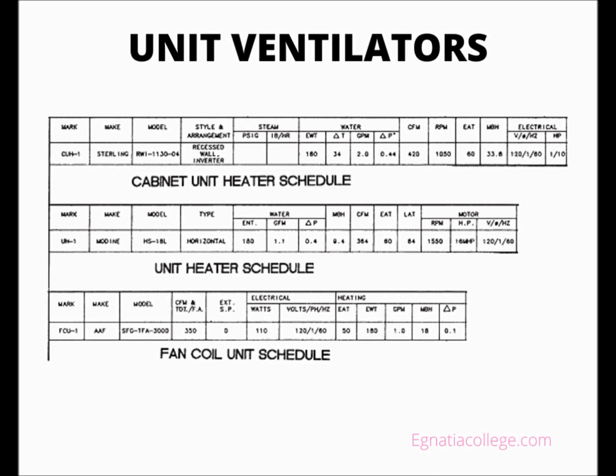The unit ventilators are only a few feet long. Yet the plans show a continuous string of equipment of some sort along the exterior walls of the classrooms. Although not labeled anywhere on the plans, the equipment is bookcases. The construction notes refer to them. The manufacturers of unit ventilators also manufacture bookcases and filler pieces that are designed to fit with the ventilators and fill the rest of the wall space. These bookcases have a false back, with space for pipes to and from the ventilators.